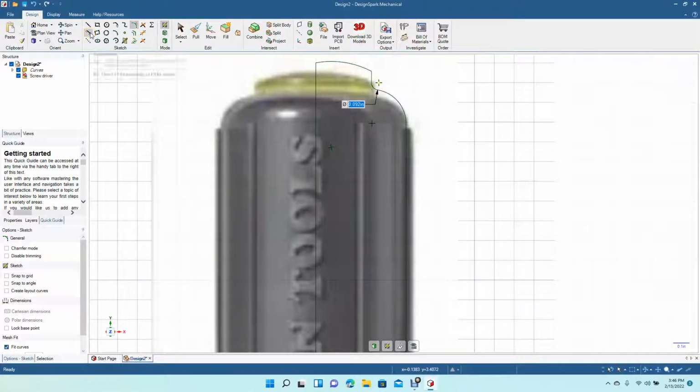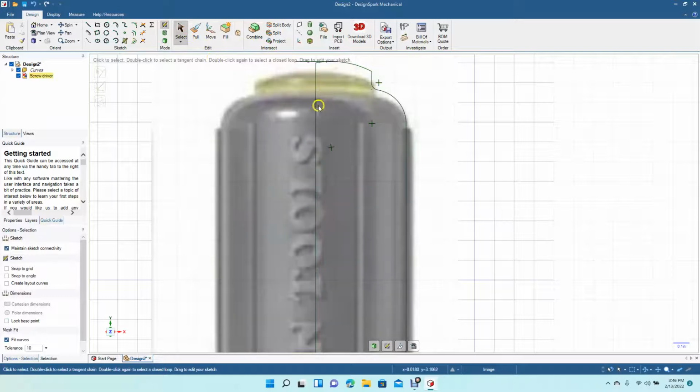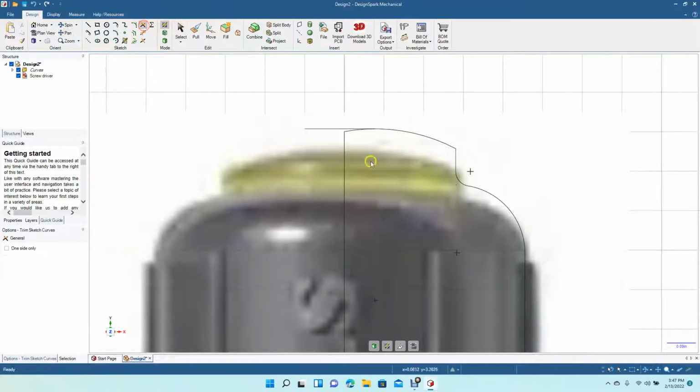And then this one we want it to be straighter. So we're going to get the tangent line, and we're going to go from up here straight across. Select to click off. Let's Control plus. Let's pan down. Okay, now we're going to go grab our create corner. We're going to select here and then select here and then select here.